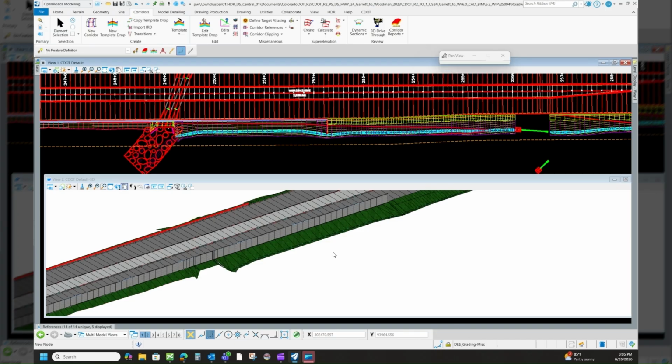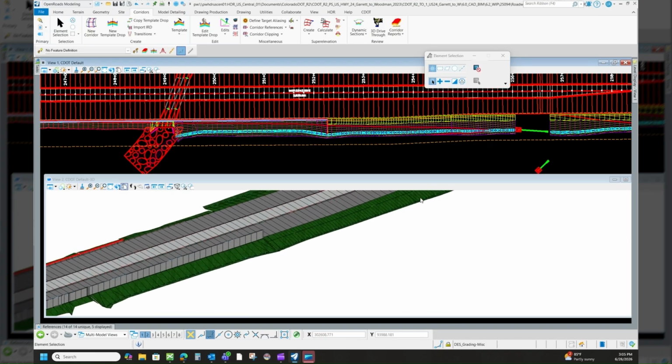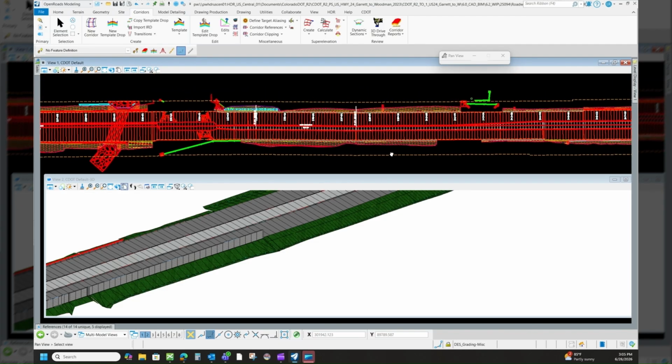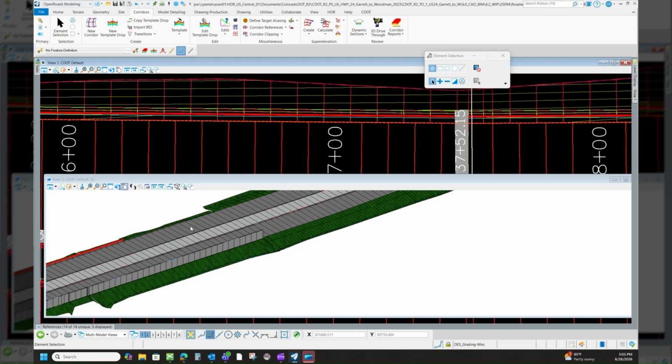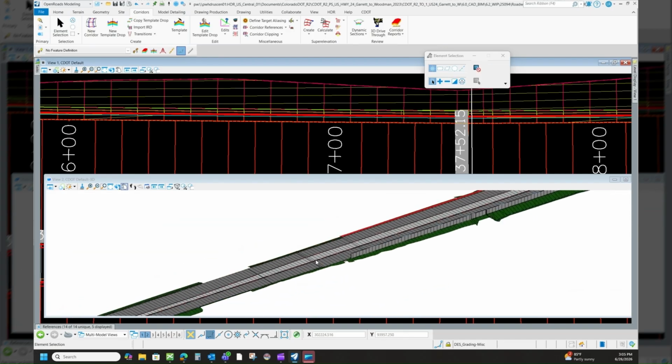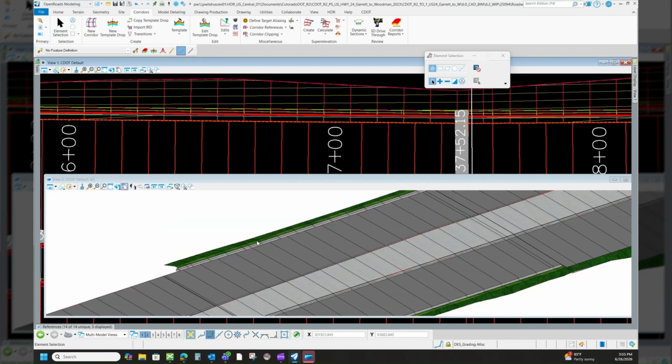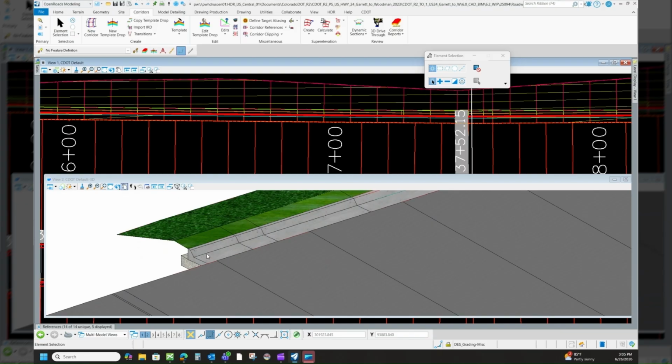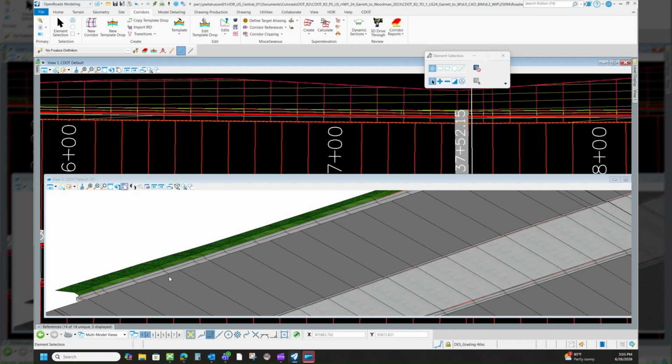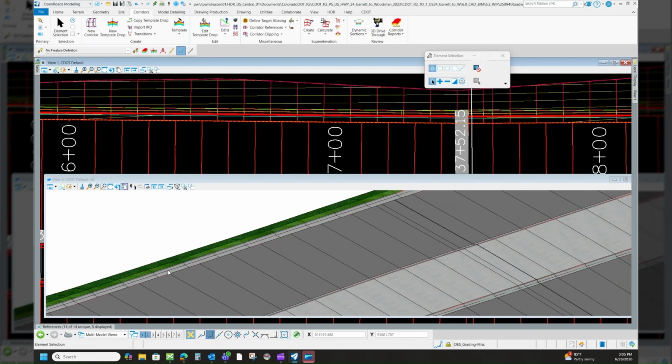So as you can see, now I put it back in. Sometimes horizontal might make more sense with curbs. Typically vertical makes more sense, but maybe it's like the back of sidewalk or something. You can just do a simple parametric that would extend your sidewalk, so then you would want to do horizontal.